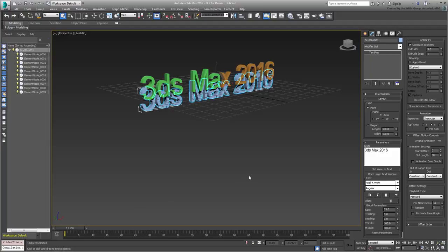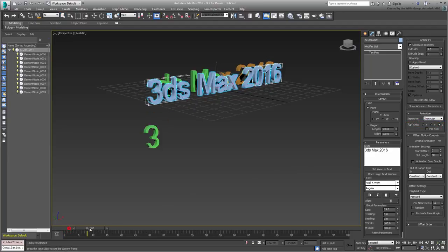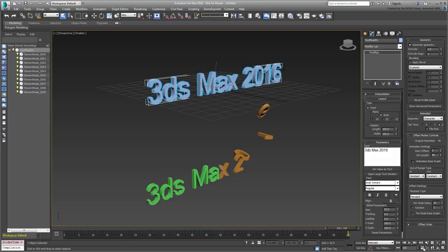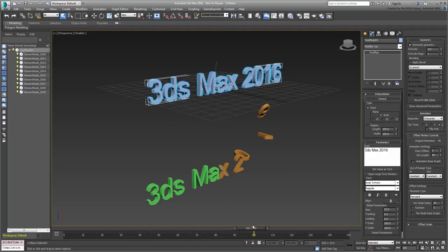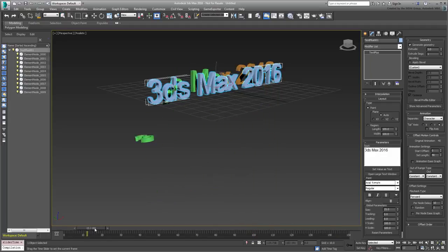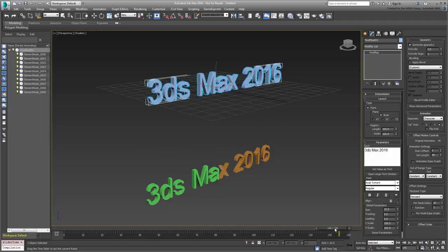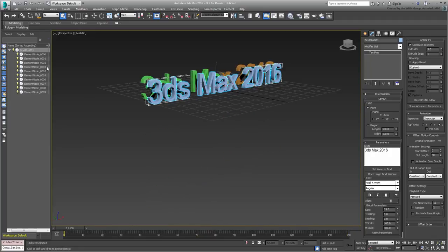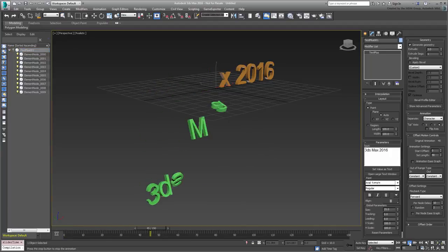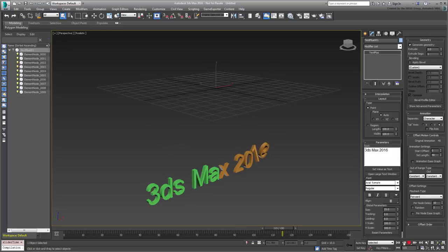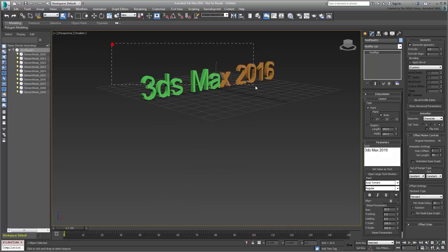Fortunately, this can be reassigned at the TextPlus level by choosing an up axis, in this case Z. Scrub the animation. You may need to extend the animation length a bit. At this point, you can hide the original TextPlus element and deal only with the animated characters. They are entities in their own right and can be edited as such, for example by centering their pivot points.